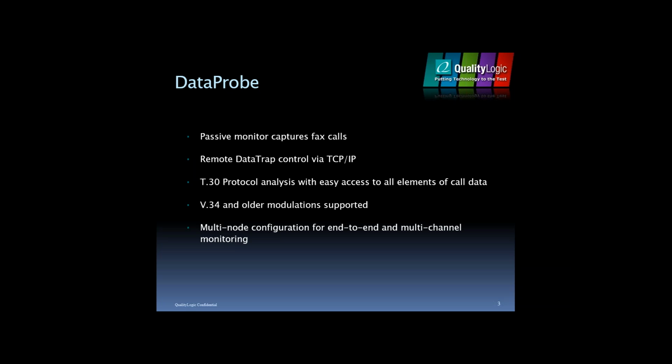T30 protocol analysis is fairly straightforward, but it's very detailed. So we're going to look at that in some detail when I actually get to the point of talking about DataProbe itself. It supports the full array of modulations, encodings, resolutions, and all of the other varieties of differential information between the different fax transmissions that are available via T30 today. We actually cover quite a few modulation resolution combinations that no one appears to be using yet.